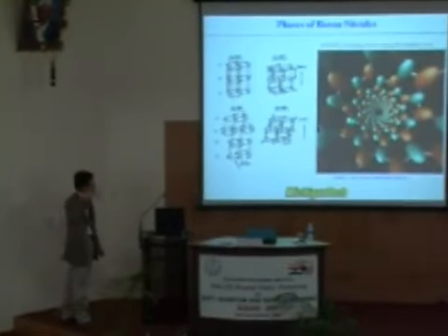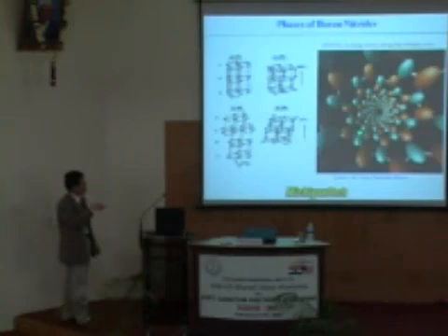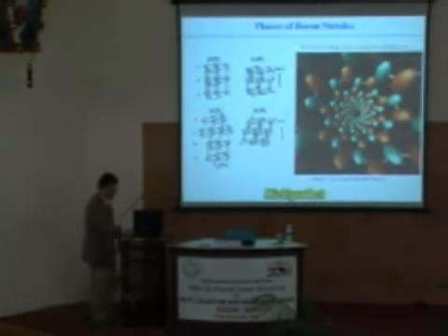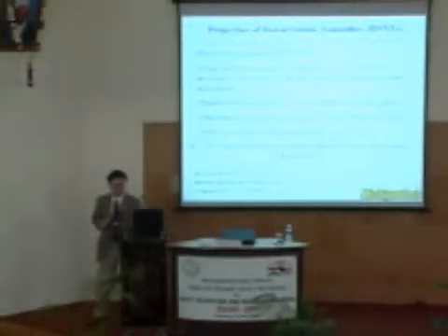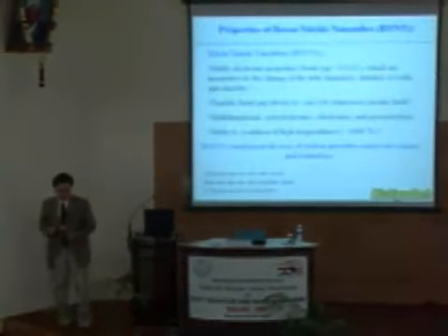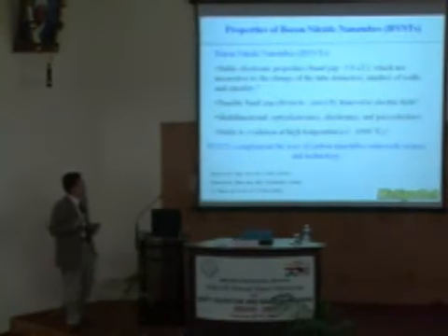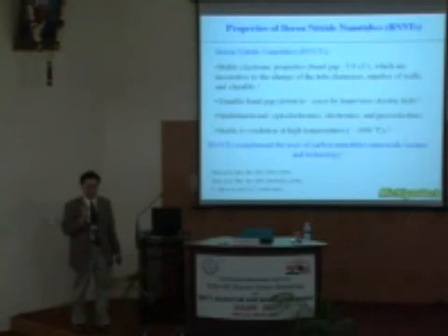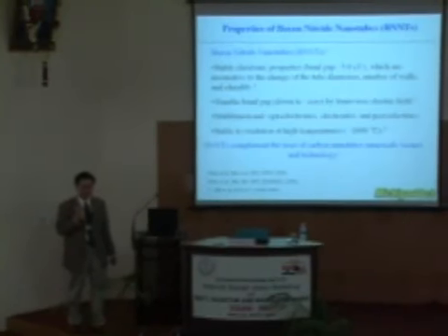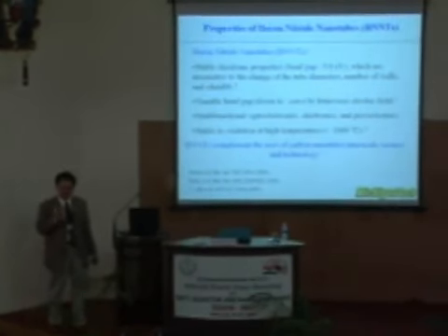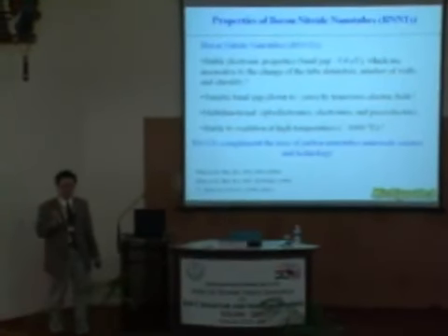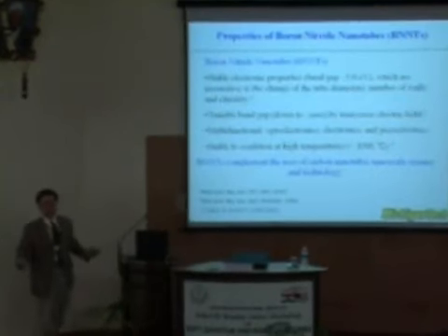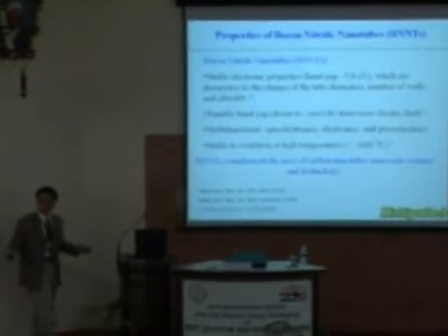Looking along the axis of the tubes here, you can see the boron and nitrogen in a hexagonal network. The advantage of boron nitride nanotubes is that, first, carbon nanotubes have a band gap which is smaller than silicon, which means if you have a heat problem in your computer now, you will have more problems if you replace silicon by carbon nanotubes, right? With a smaller band gap, it will be noisy to operate your system.